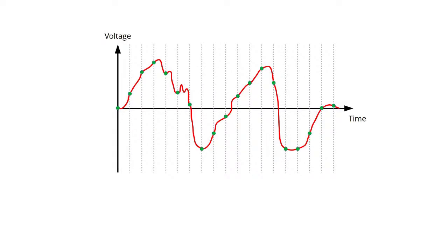Everybody's heard the term sample rate, which is the number of readings per second. This imposes an absolute upper limit on the frequencies that can be represented at the sample rate we're using. So here, this detail is lost. This upper limit is known as the Nyquist frequency and is half the sample rate. If we try and represent frequencies above this, they actually appear as frequencies below it. The simplest way to think of this is that they are reflected down from the Nyquist frequency.